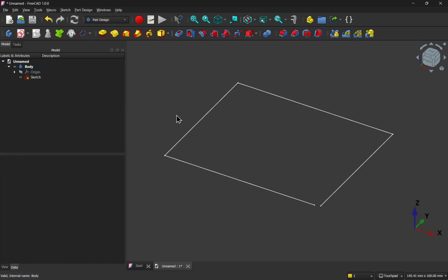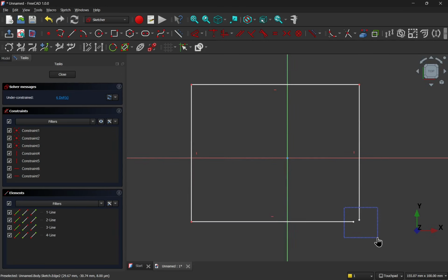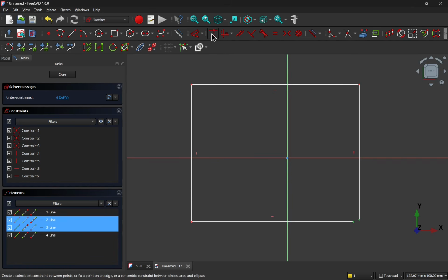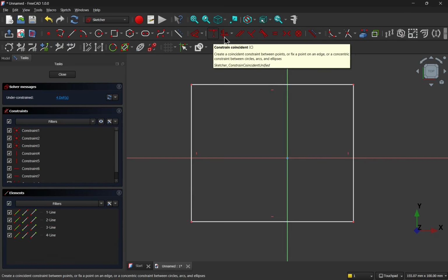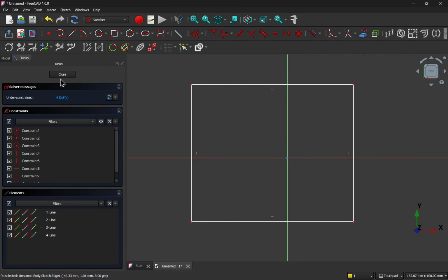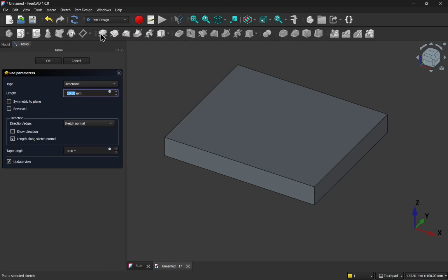To fix this issue, go into the sketch, and we click and highlight those 2 points. And we use the coincident constraint, and this is a combined constraint. This combines both coincident and something called a point on line constraint, which we'll learn about. Click that, those two are together, and now this will extrude using the pad operation. It is extruded back to a solid.